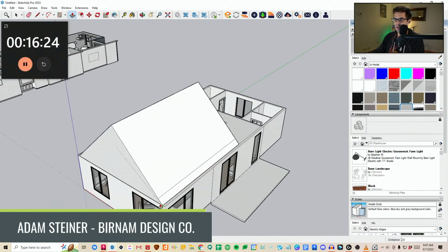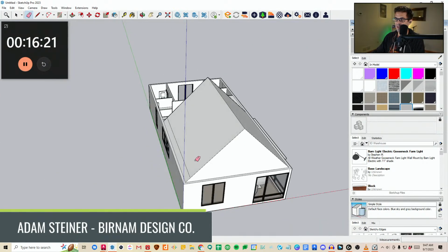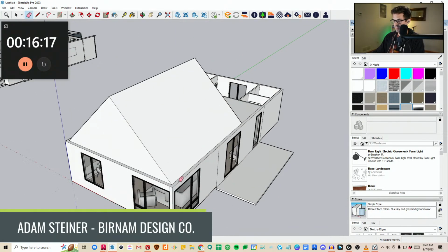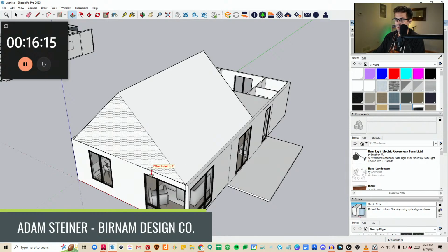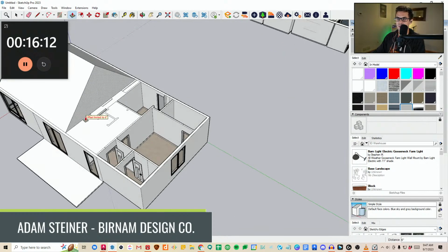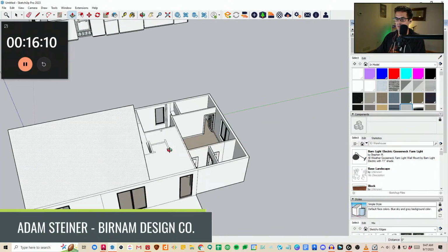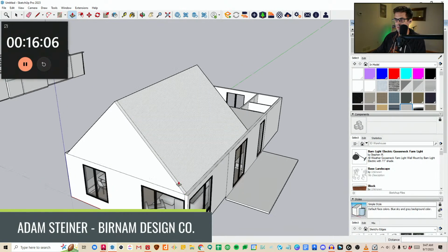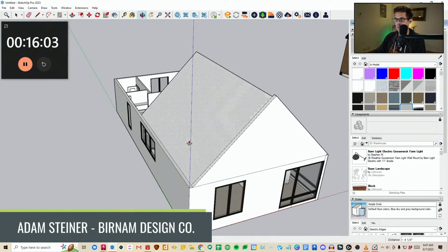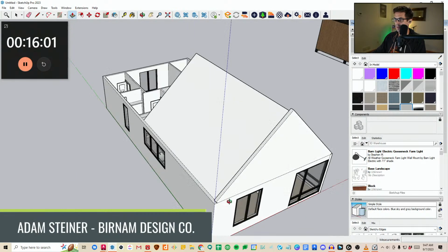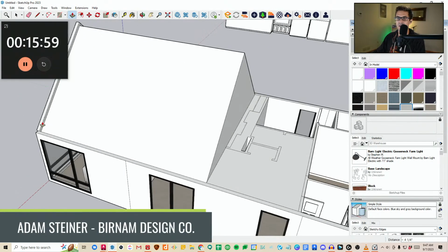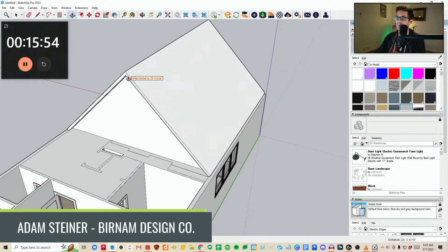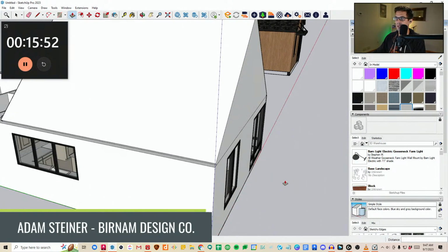Okay, I'm going to push that across. So that has our interior space. Actually going to bring that out. All right, I'll leave that. So what I'm doing now, sometimes you need to box it out, or the rendering will bleed light through those corners.